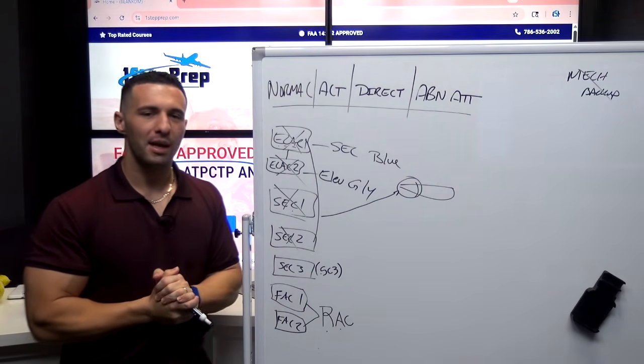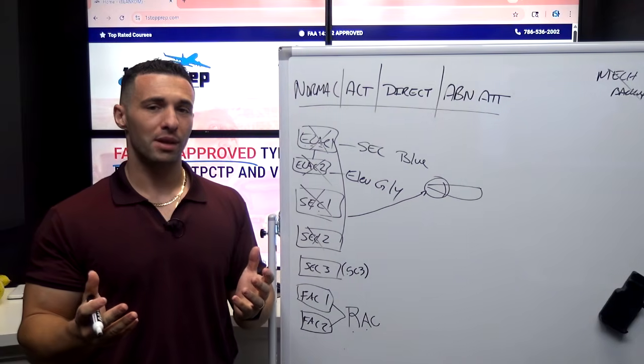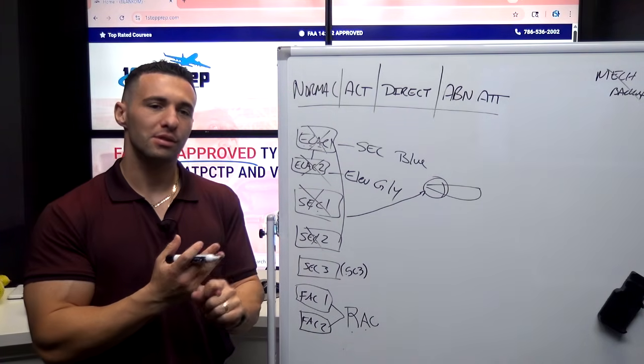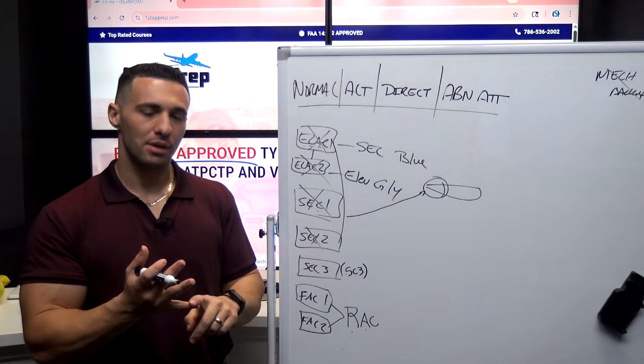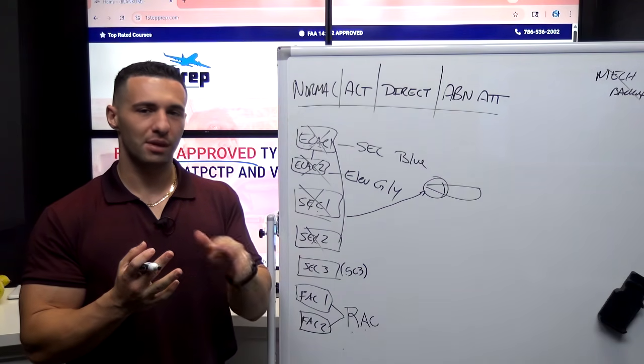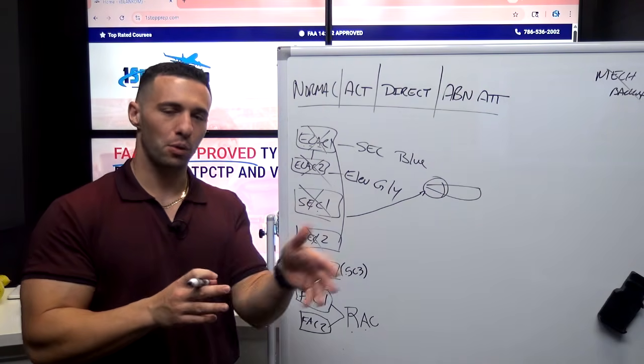Now, in mechanical backup, the means by which I have to control the aircraft is basically the trim. So I'm controlling the stabilizer. And then I still have rudder input, which is great for yaw roll coupling. That's another aerodynamic term where basically a yaw input induces a roll.